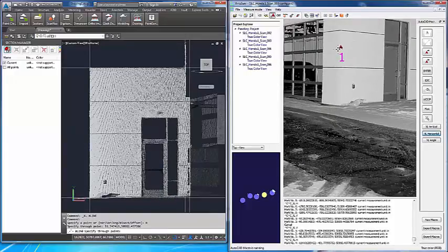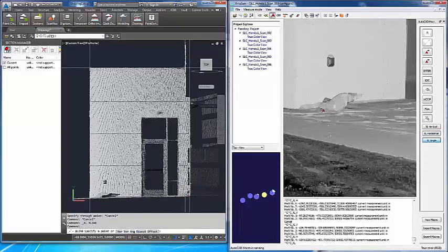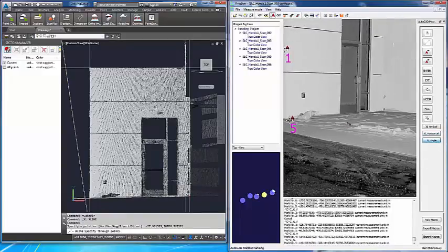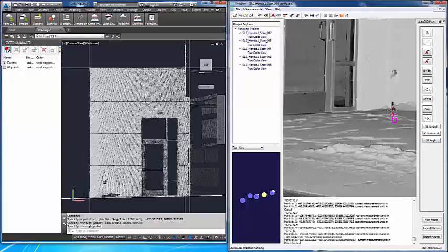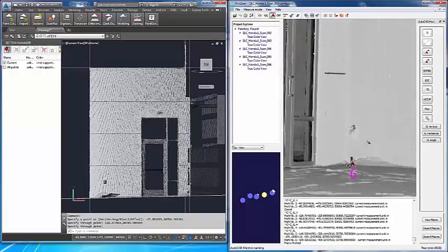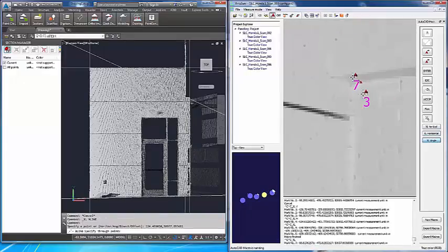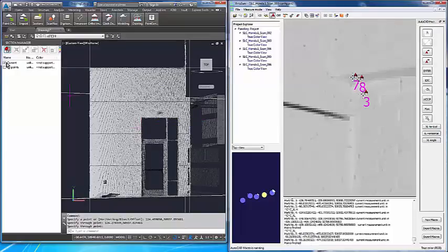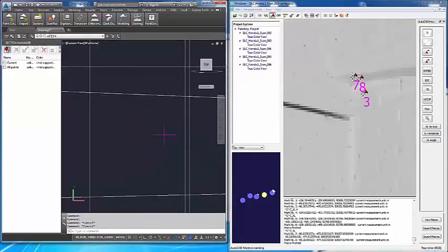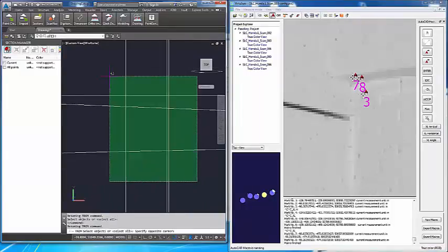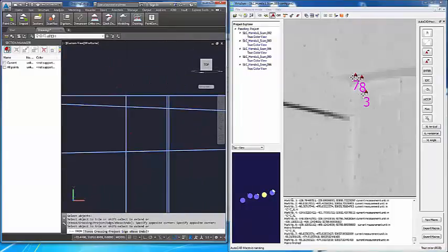the ground, but we can see that that's kind of sloping, so we may want to use this XL angle instead, which just allows us to create this infinite line, the X line or construction line, at an angle. We can do the same thing here, XL, 1 and 2, and now that we have all of our sides, we can just use good old AutoCAD trim to just tidy this up here in CAD.